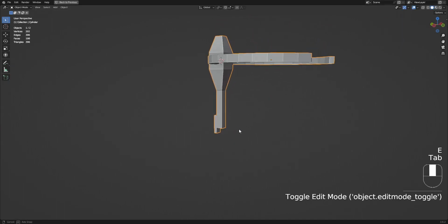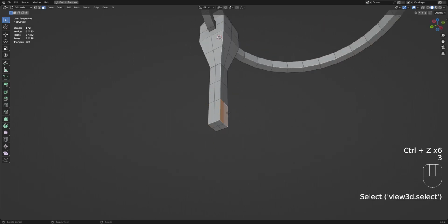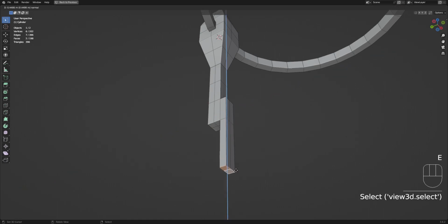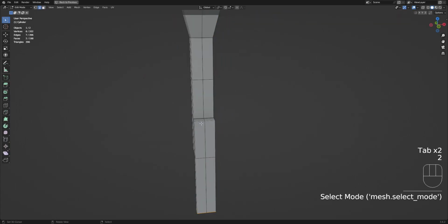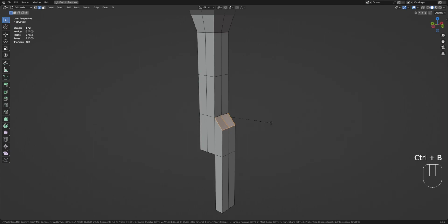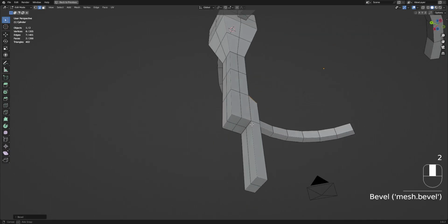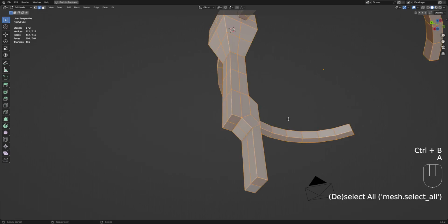The subdivision when using the Random Flow operators works only with quads and tris, so not n-gons. You can see in my videos that the base meshes are always quads unless not needed.